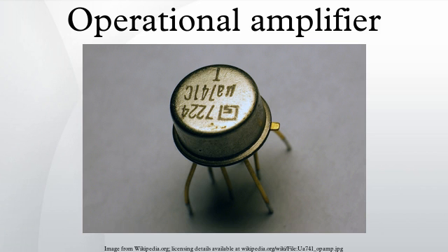Negative feedback cannot, however, reduce the limitations that a load in conjunction with Rout place on the maximum and minimum possible output voltages. It can only reduce output errors within that range. Low impedance outputs typically require high quiescent current in the output stage and will dissipate more power, so low-power designs may purposely sacrifice low output impedance.